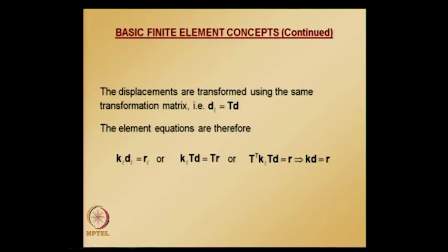Once nodal displacements are known, element quantities, displacement, axial forces, moments, shears, at any point along an element can be computed using shape functions and their derivatives. For each element the global displacements must be transformed into local displacements before performing the element level calculations.